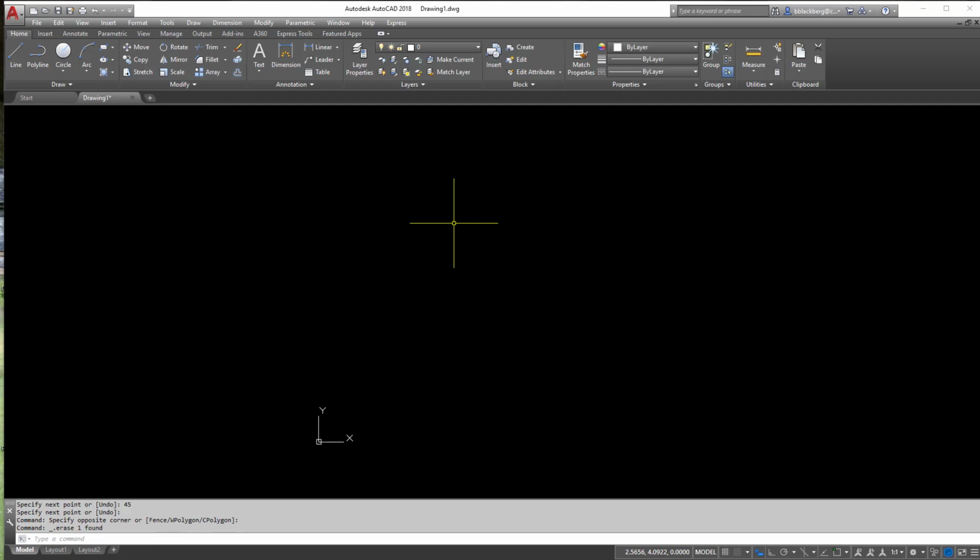Now, so that's lines using dynamic input. So now let's say you have to draw something, and I'm going to turn dynamic input off now, and all my angles are going to be 30 degrees. So there's another command down here called polar tracking. You'll notice it says polar tracking F10. F10 is the quick shortcut you can hit on the keyboard to enable polar tracking.